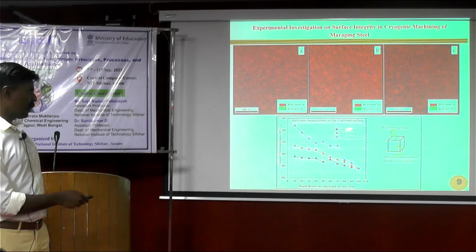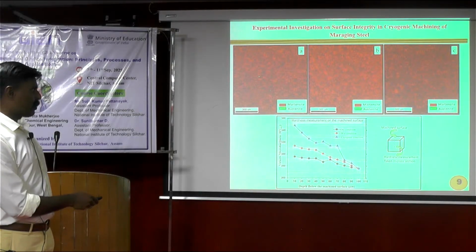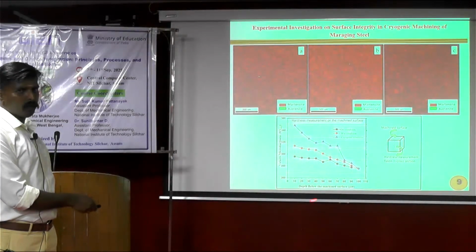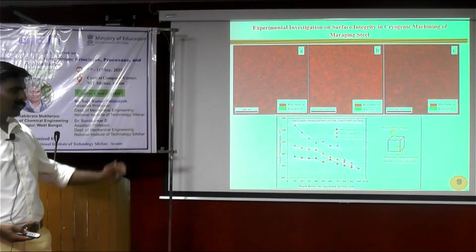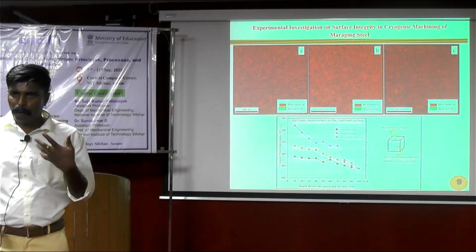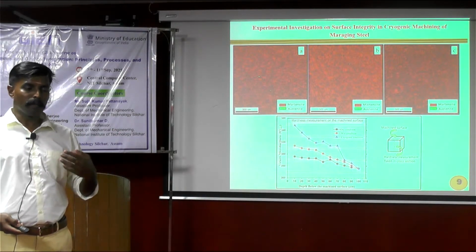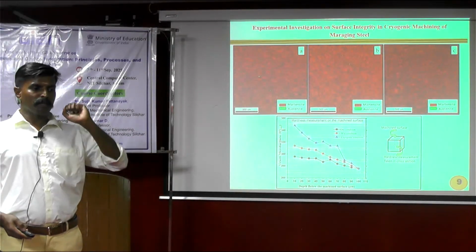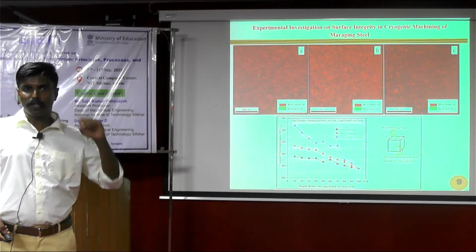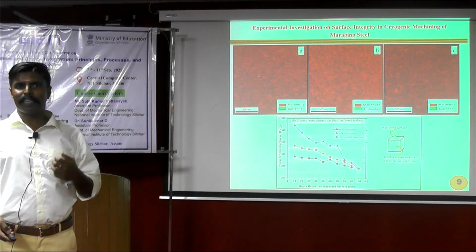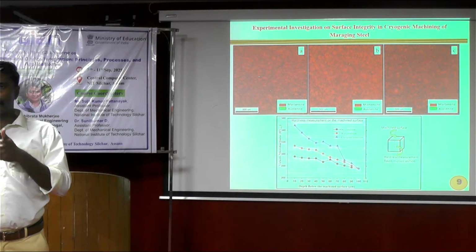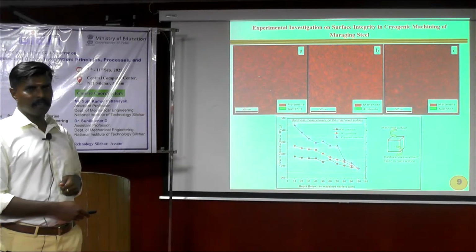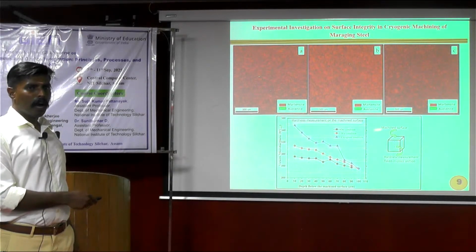Okay, but next to the wet condition, the dry condition is showing very poor hardness. So that implies that if you want to enhance the properties of the machined surface, during machining we always think that if residual stress is going, then some deformation happens and strength should not go down. Always our criteria is strength to retain. So if you maintain the cryogenic condition, you will get a good hardness value.